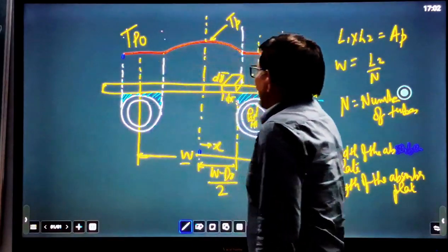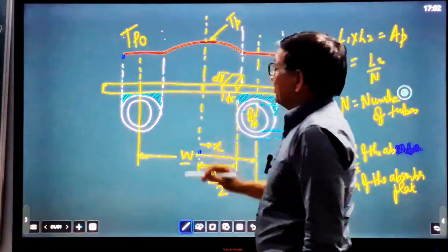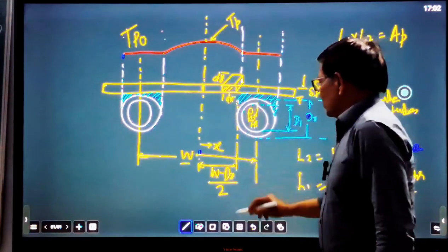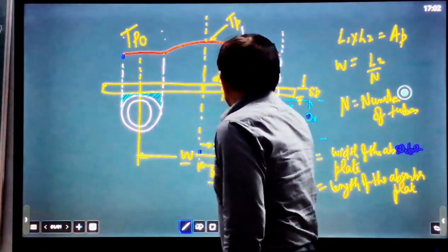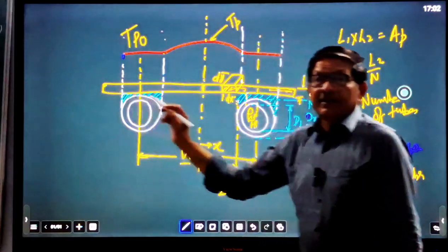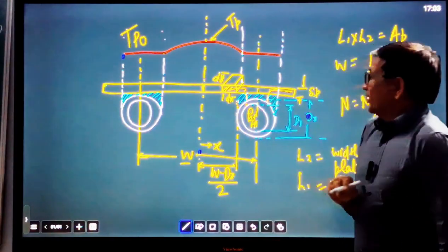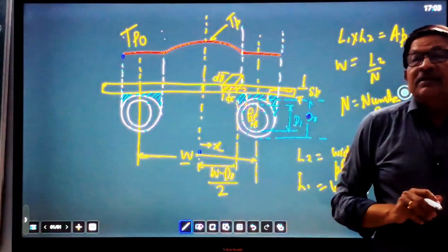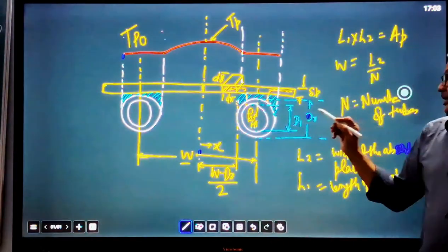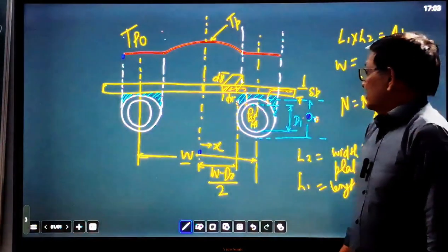And this temperature is varying between two tubes. Here the temperature will be maximum at the center point, and as we move, through conduction heat is going to the tubes. So here heat is going to the tubes like this. From here also, because from both sides heat is conducted from the absorber plate to the tubes. So this is the arrangement to explain collector efficiency factor. And here are two tubes. The internal diameter of the tube is di and the outer diameter of the tube is do.